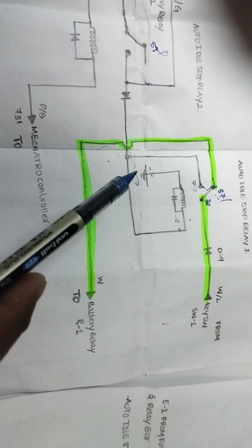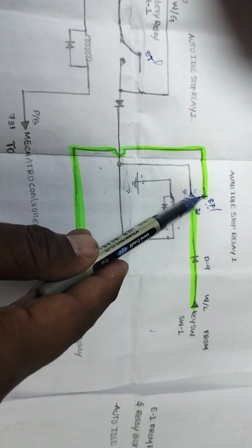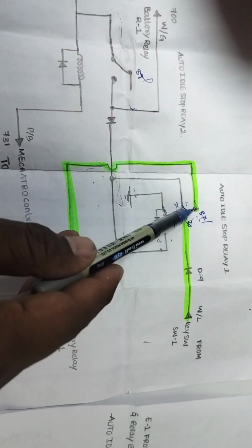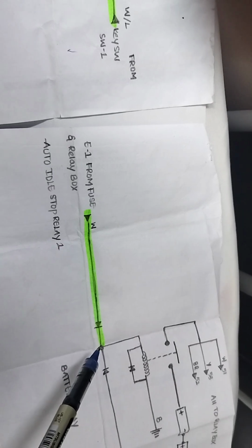You may have doubt that two power supplies are coming, but we don't have any issue. The thing is, we have diodes in between for safety purposes. If the power supply comes from this area, from here it shorts here and to this, and see this diode, it goes to the relay. That is for safety purposes. So if supply comes through this, it has only one load, and power never comes back. This is only forward bias.